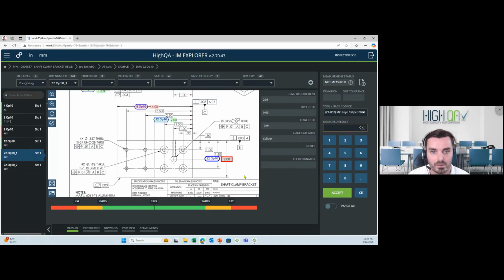So that's the shop floor interface. Again, this is for your manual calipers, mics, stuff like that, where as you're making the measurements and inspections, record the data digitally, and that'll flow back into the main system paired up against the inspection plan that we had already created.